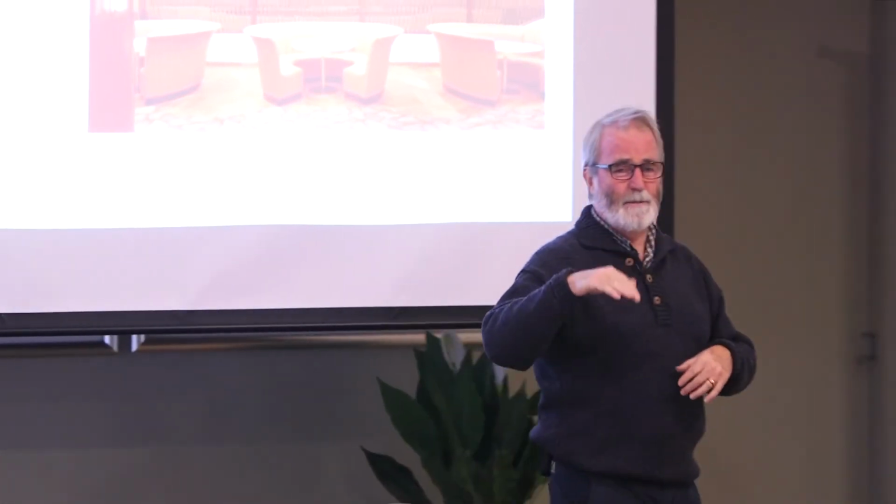You then have a whole series of fire indices which will determine where you can use particular materials depending on path of egress and a range of other similar considerations. Most wood bundles together, so none of the species that we're going to be looking at is actually going to be much higher or lower than any other species that you're going to be able to use. There is a bit of a boundary line on spread of flame, but most of that data is in those species information sheets. And certificates are available if you need them.